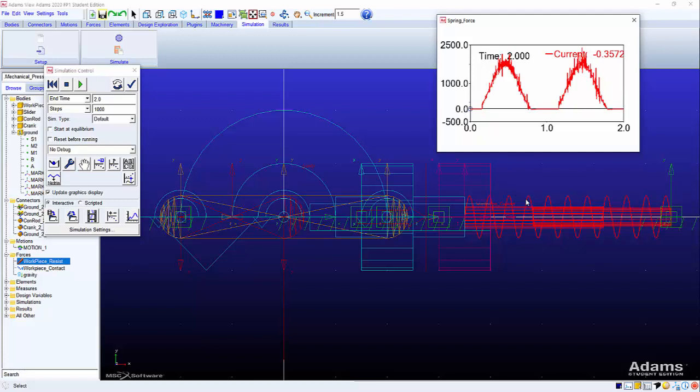Once the spring reaches the maximum deflection, and this will be close to the end of the cycle of our piston, now what is going to happen? The piston will start to retract, going back. So the contact force between the spring and the slider is going to push our workpiece against the slider, maintaining the contact force, but at the same time, because the deformation of the spring is decreasing, the spring force will also decrease. The contact force is creating this noise, so we don't see a very smooth resistance force. The contact will continue until the spring reaches the undeformed position, while the piston is moving backward. Once they lose the contact, the spring force will become 0. And then this will be the end of the first cycle.